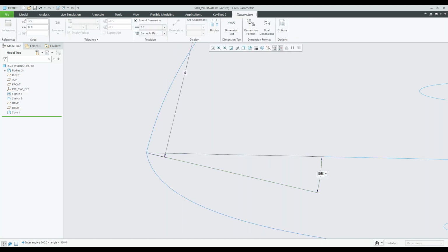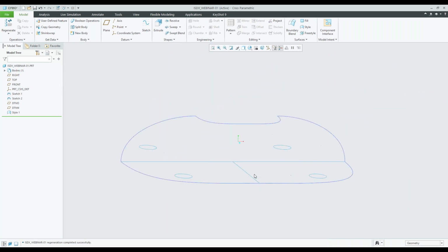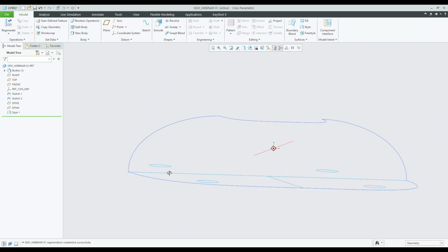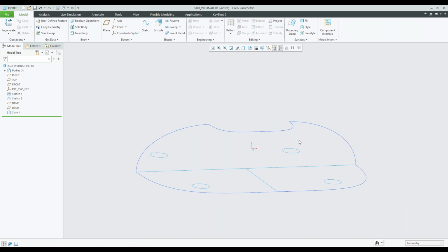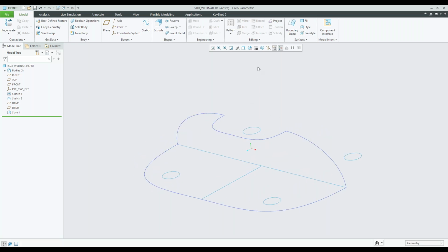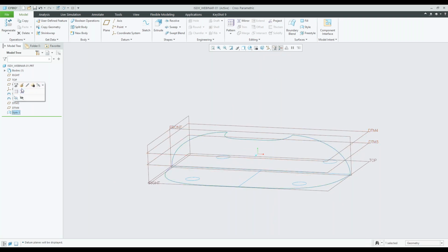I just want to show you guys that once you exit out of that ISDX style tool or feature, you can go back and edit those dimensions if you select those boxes. Let's go back in here. So next from here, we're going to go ahead and create a third curve, or second, third, fourth, fifth curve. Let's go into the style 1 feature.